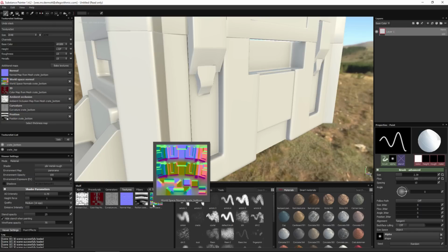So that's going to close out this video. We discussed how baking works inside of Substance Painter. We discussed the various options for each baker, and we also discussed how the ray casting is working and how you determine that max frontal and rear distance here inside of Painter.